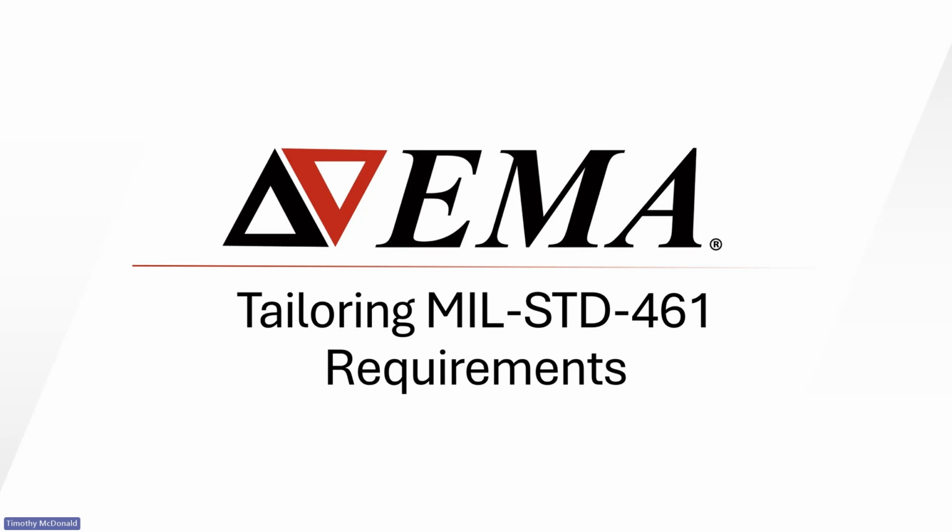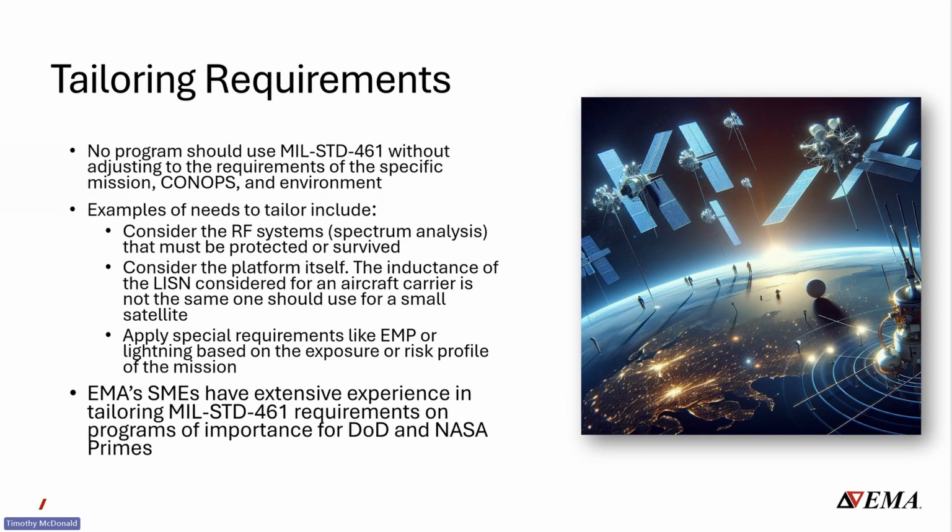You can imagine that the inductance of a very long power distribution cable on an aircraft carrier is going to present a very different inductance than a short cable on a small satellite. So it's very important to tailor those MIL Standard 461 requirements to your platform, concept of operation, and operational environment, and to closely collaborate on that with your customer. However, sometimes making that tailoring requires deep industry experience, and some customers don't always have that on internal teams. So EMA can help with those cases.